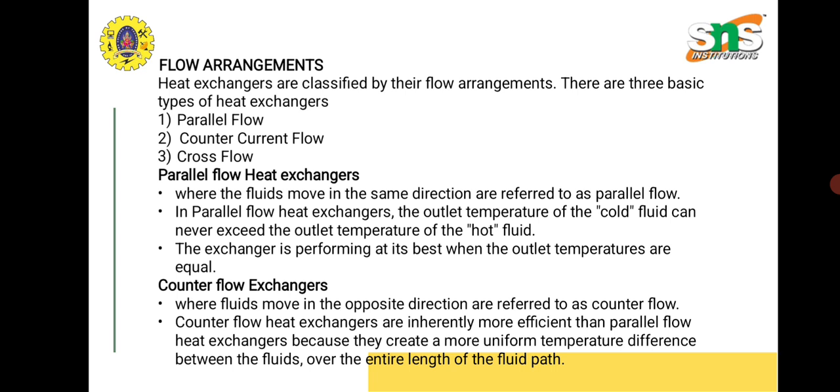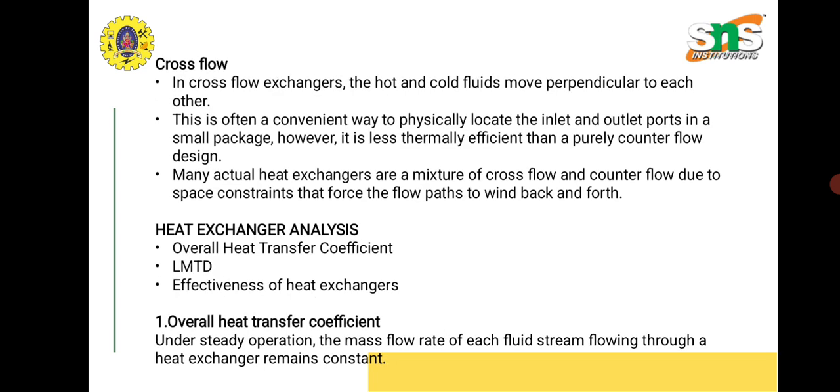Counterflow heat exchangers, where fluids move in the opposite direction, are referred to as counterflow. Crossflow. In crossflow exchangers, the hot and cold fluids are perpendicular to each other. Heat exchanger analysis: overall heat transfer coefficient, LMTD, effectiveness of heat exchangers.